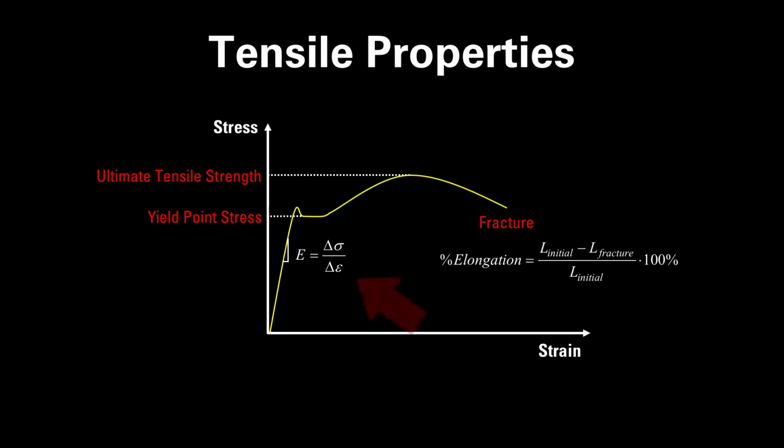The elastic modulus is determined at relatively small loads where the stress is proportional to the strain. As the strain increases, the material will begin to yield. Upon yielding, it will take smaller and smaller increments of stress to produce a given increment in elongation. For some materials, yielding will result in a zone where the stress will not increase with an increment in strain. This stress is determined as the yield point stress.